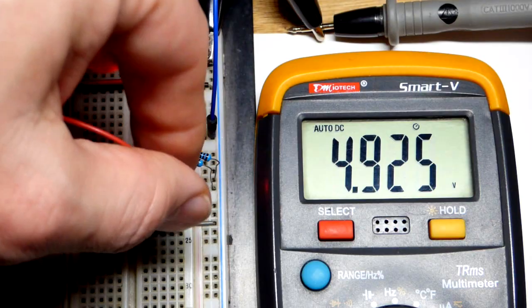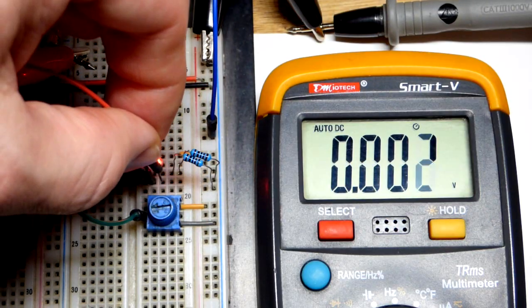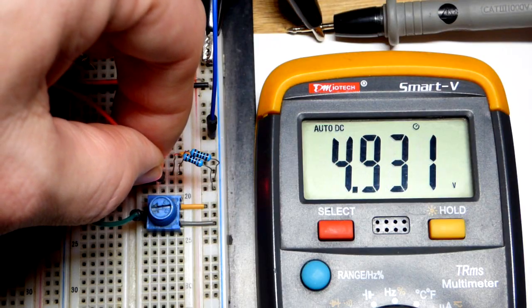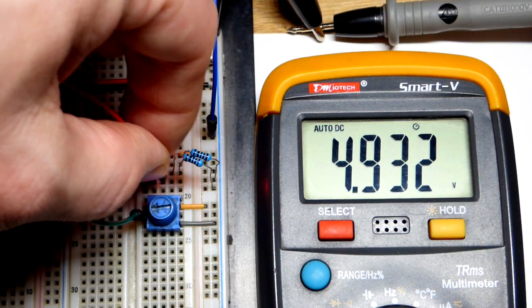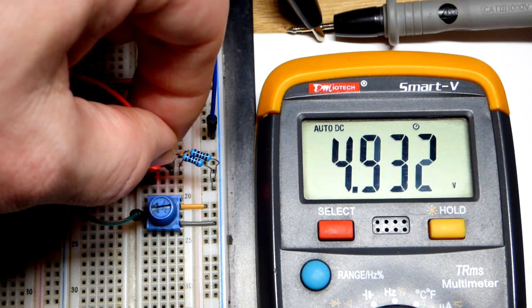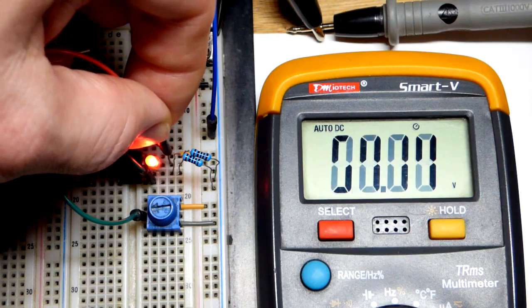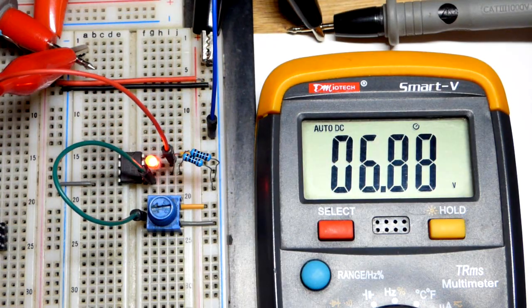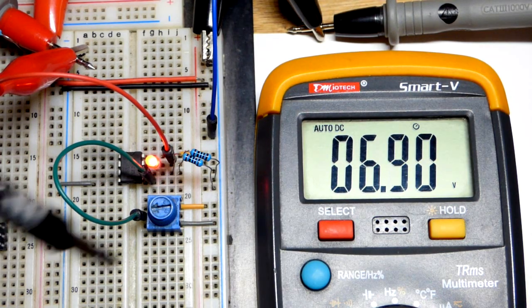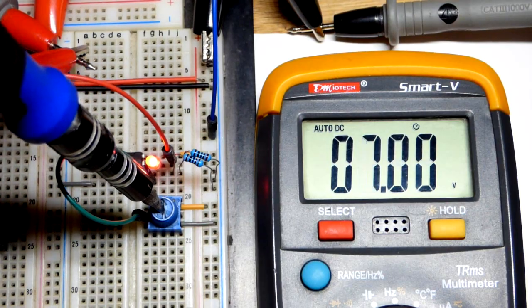So there we got 5 volts, as we said before, at the output, and that's going to lead to 5 volts at the non-inverting input, because that's a direct connection right there. But then the op amp's going to do what it can to give you 5 volts at the inverting input, and to do so, it has to take that voltage plus whatever the load needs. So we got 7 volts. But now we will be able to turn the trim pot to 10 volts, and we can measure that as well.